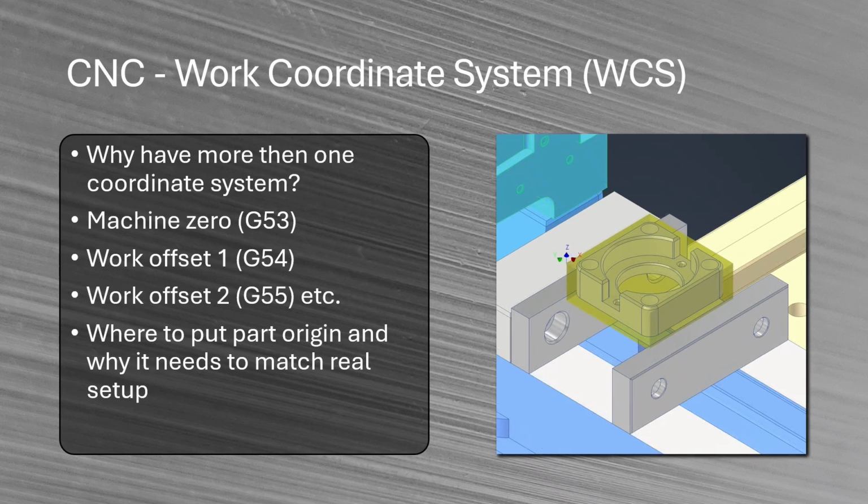This I would say would be the easiest, of course, because you just take the left edge, take the top edge, and take the top. So this is best. This is also the least precise, because we're not taking into account any of the other edges, but for the first operation, it doesn't really matter. We're just roughing, and every edge will be new, so to speak. So it doesn't really matter. It's best to just pick the easiest.